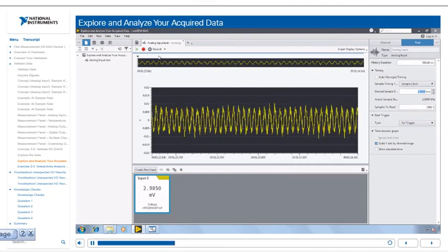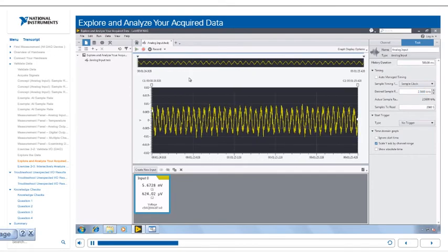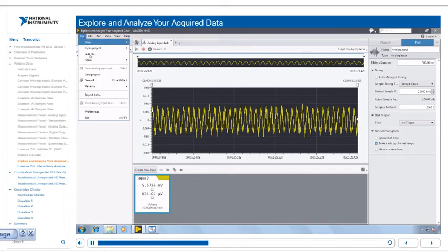I will begin by capturing data from the measurement panel by right-clicking the data and selecting Capture Data. This saves the data as a data item in the Capture Data tab, and I can rename the captured data with a more descriptive name. I can select File, Save All to include this captured data item as part of my project. This is a convenient way of saving interesting data for future use.